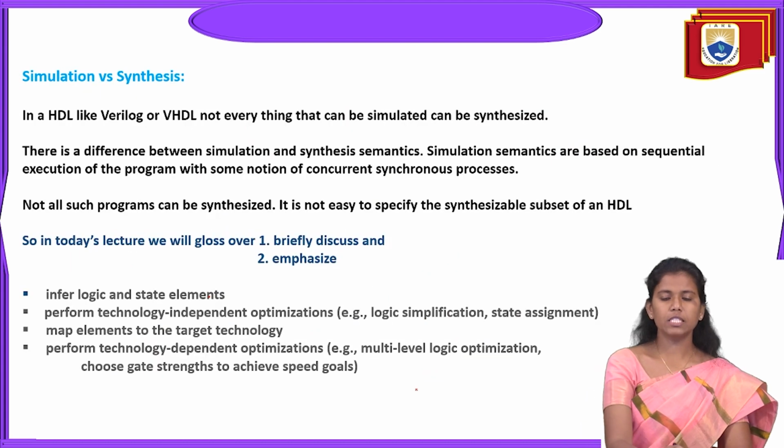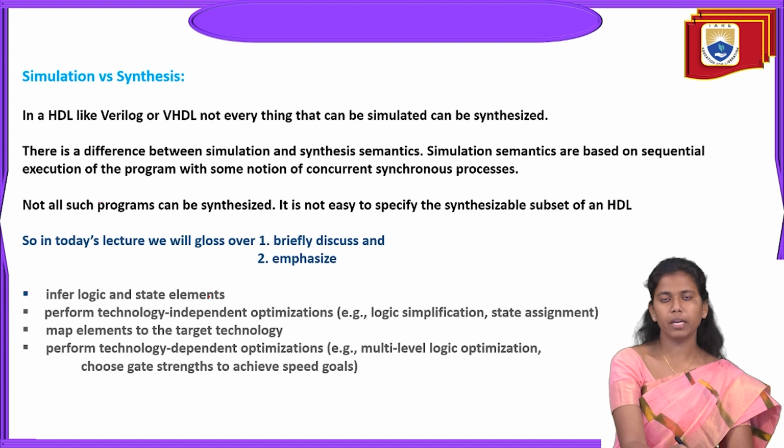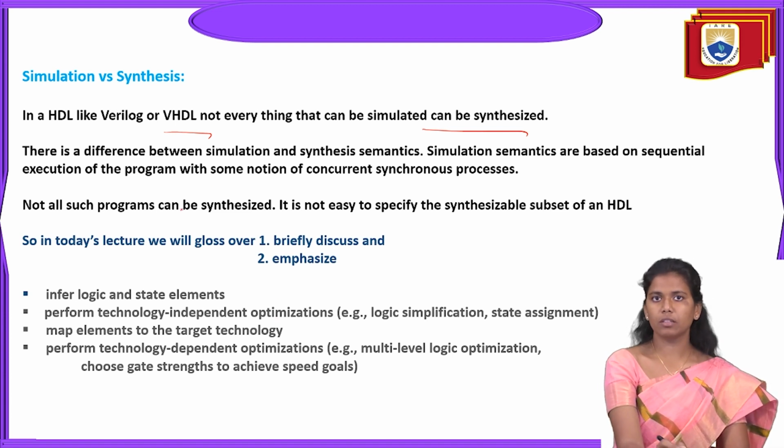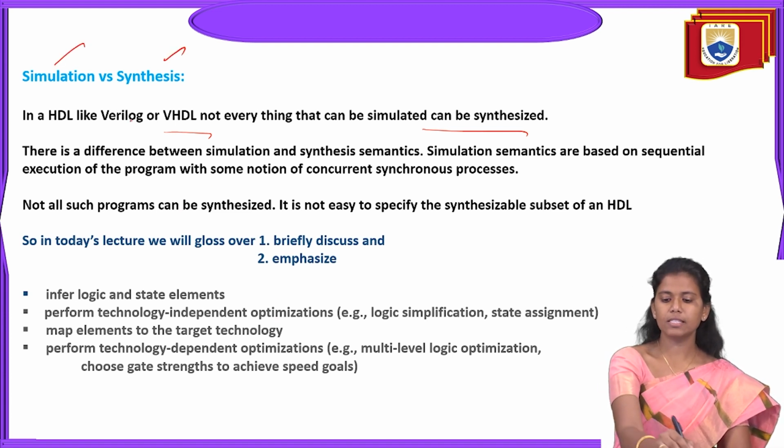And then we will see simulation versus synthesis. Simulation versus synthesis is about the fact that in Verilog, like VHDL, not everything that can be simulated can be synthesized. So there is a difference between these two terms, simulation and synthesis.